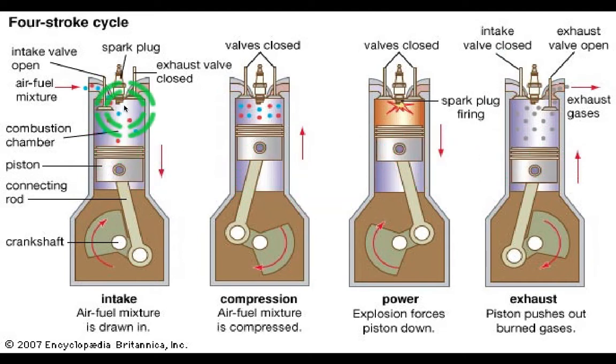Because if you felt it, then you're gonna know what an overlap is, how a cam can disturb you, and how you have to know it, right? Just like a rule of thumb: which stroke happens after what and stuff like that. So always remember that intake is always happening after exhaust.